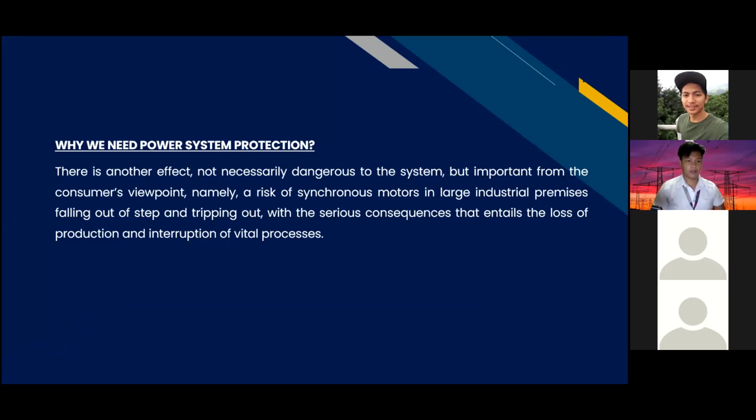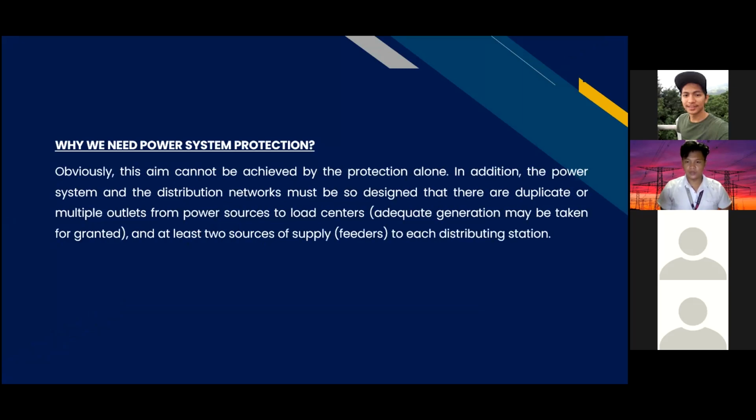There is another effect, not necessarily dangerous to the system, but important from the consumer's viewpoint, namely a risk of synchronous motors in large industrial premises falling out of step and tripping out, with the serious consequences that entails: the loss of production and interruption of vital processes. It is the function of the protective equipment in association with the circuit breakers to avert these effects.